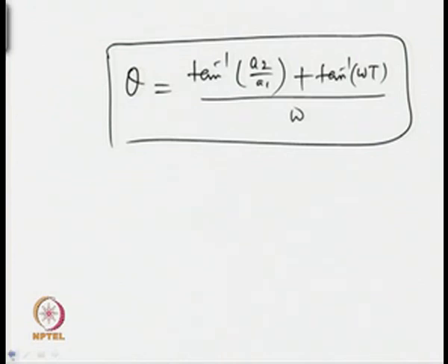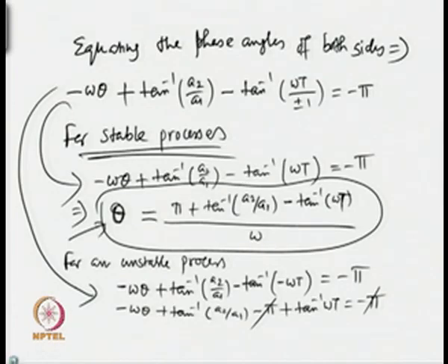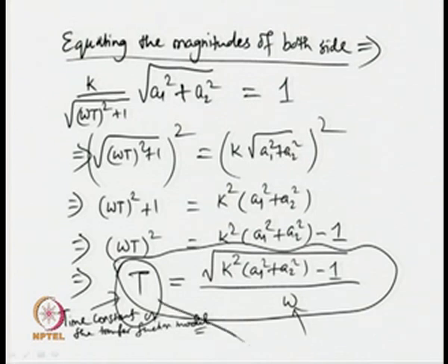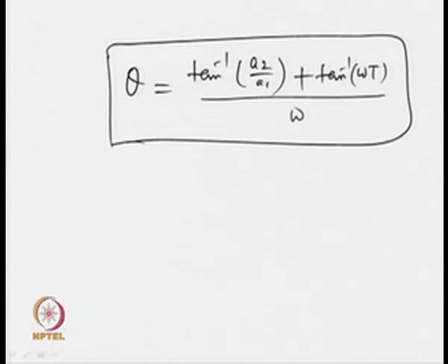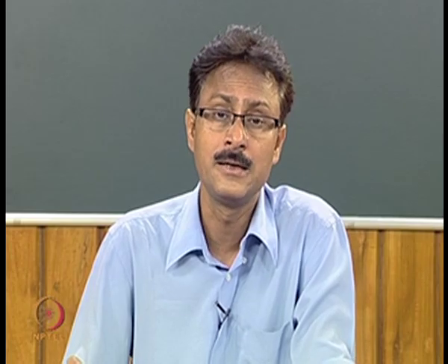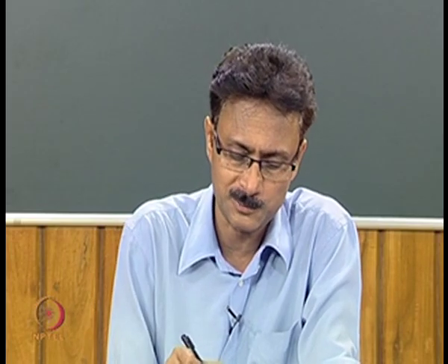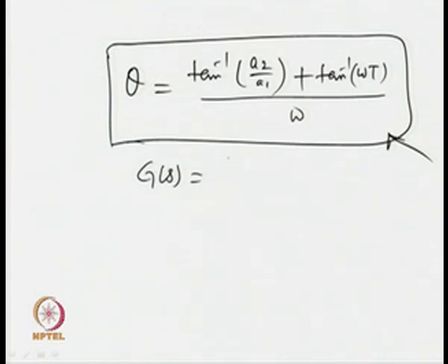So, when the dynamics is having an unstable pole, at that time please make use of the two formulas we have derived, the T and the theta given by this expression, to estimate correctly the parameters of the transfer function model, that will be for an unstable process k e to the power minus theta s upon T s minus 1.